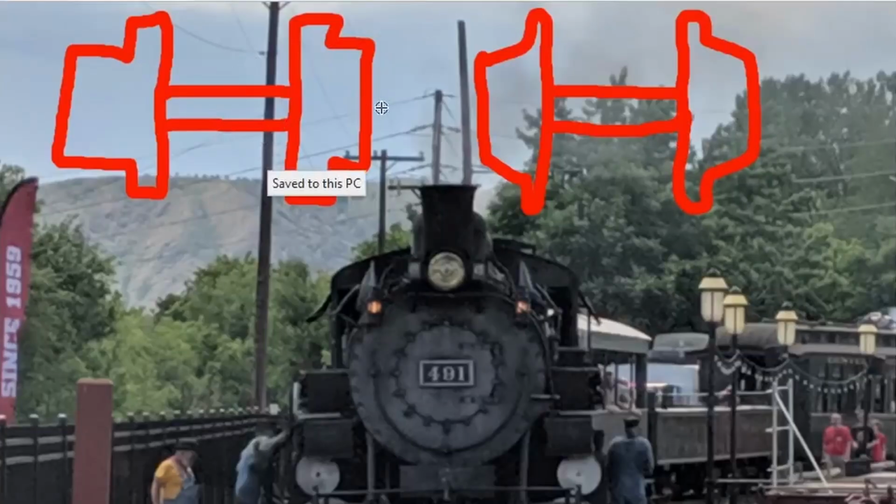So when you look at a wheel set on a train, it's not just flat, flange, flat. It's actually tapered so that it gets bigger as you go towards the flange. And so that means that typically the rails are riding somewhere in the middle, but as the train goes around a curve one way, it'll start to rock the one way until it hits the flange, or it goes the other way, it does the same thing.